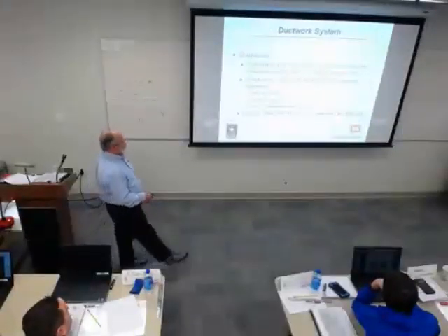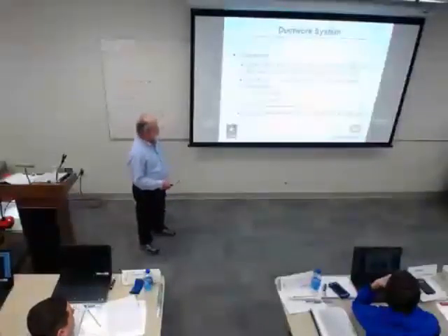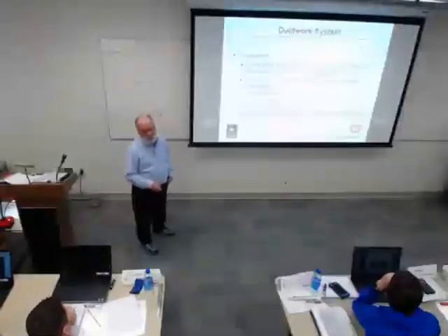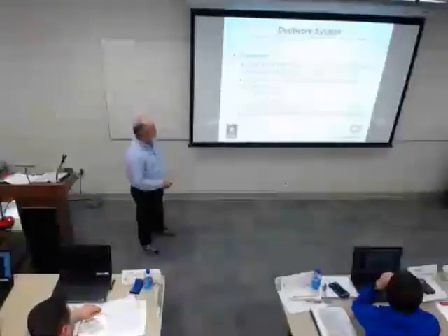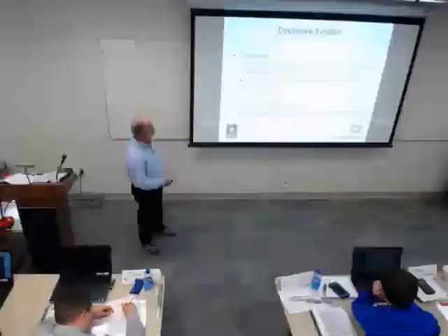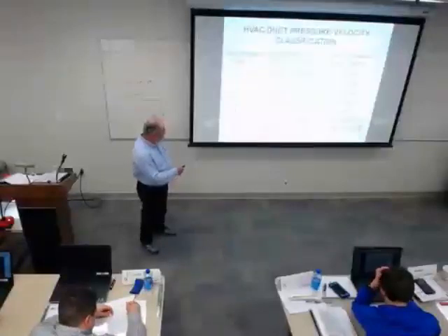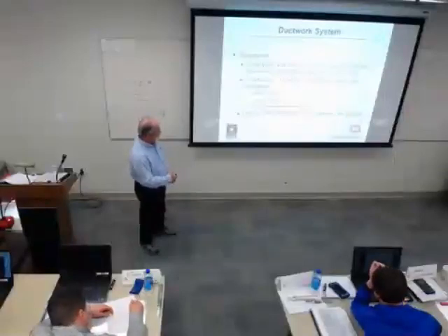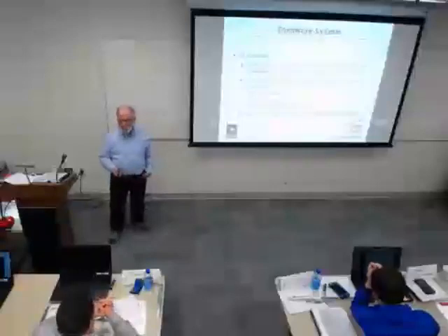There are standards, sheet metal, SMACNA, Sheet Metal and Air Conditioning Contractors National Association. You can get that on the Whole Building Design Guide. You can download some of their stuff, really handy stuff. The duct standards tell you about how things are supposed to be made. And so if you're doing QA stuff and you want to see if it's right, that's a good source. And here are the standards. And how many have access to the Whole Building Design Guide?